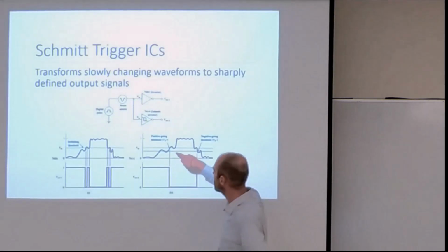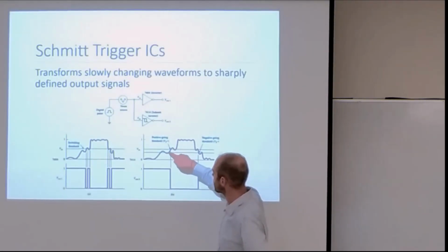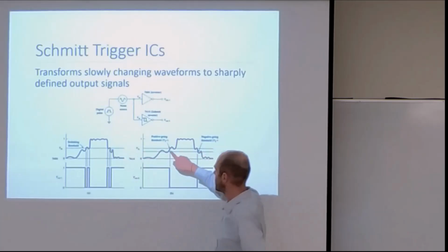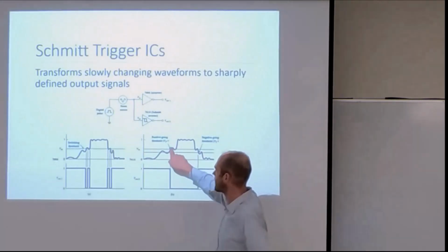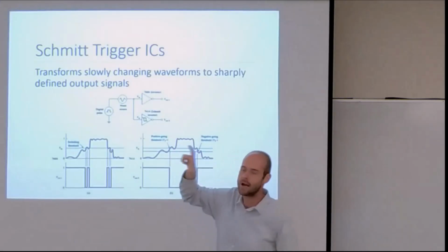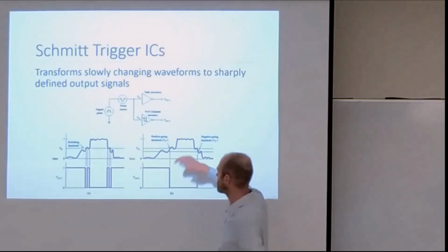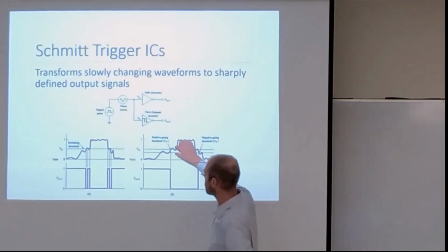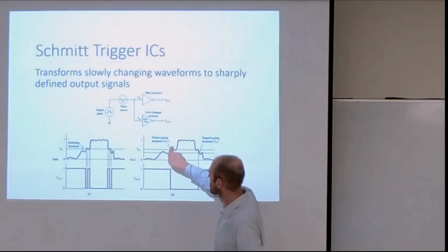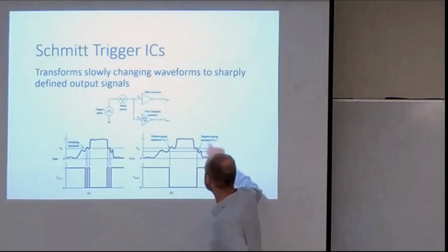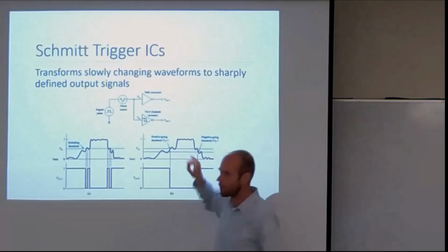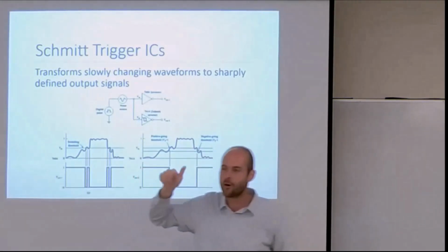So in this intermediate region you're not flipping back and forth at a single threshold. Even if you dip below your positive-going threshold, you don't reach the negative threshold, because they're separated by a space where the change doesn't occur. So if your signal is a bit noisy, you're not getting a rapid toggle back and forth.